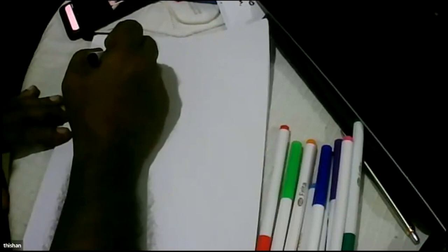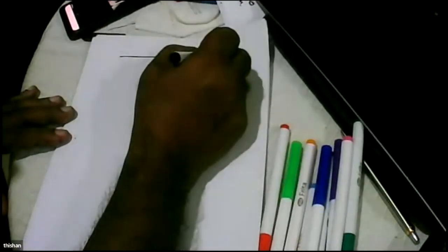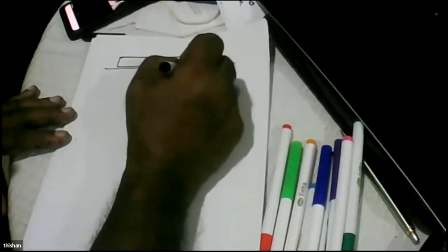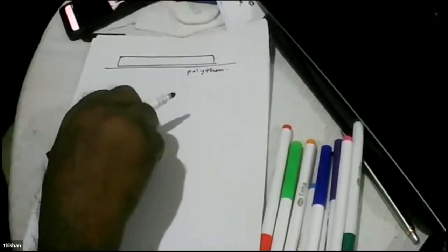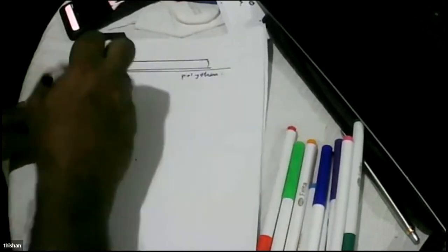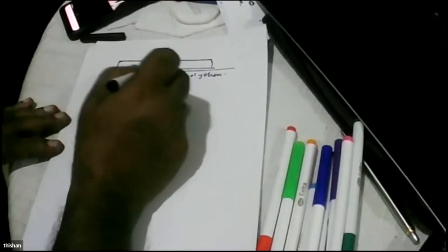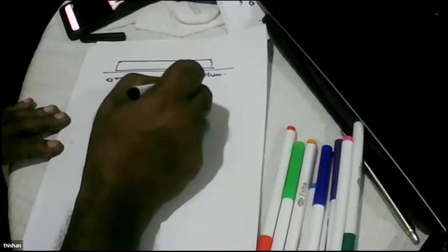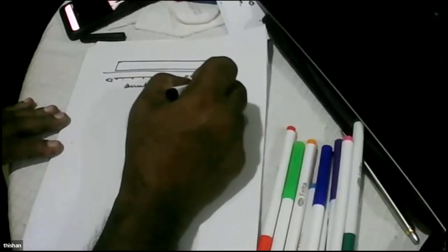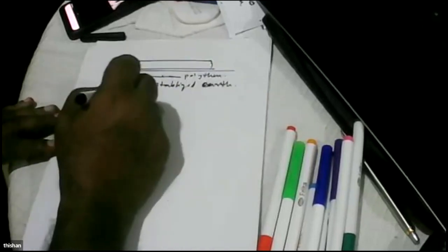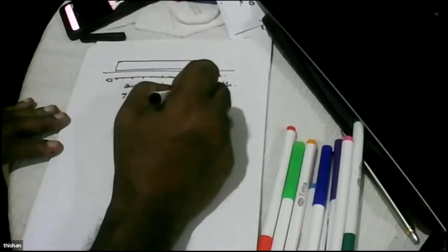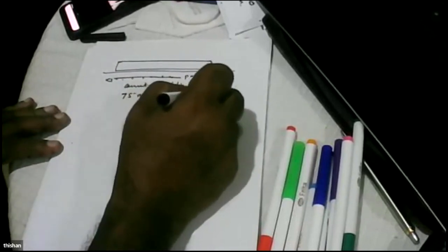Now what you have to see is how we are going to cast it. Two meters long, we lay a polythene. We first make a perfectly level surface. And how you make a perfectly level surface is, you can have cement stabilized earth of something like 75 millimeters and compact it to about 45 millimeters.